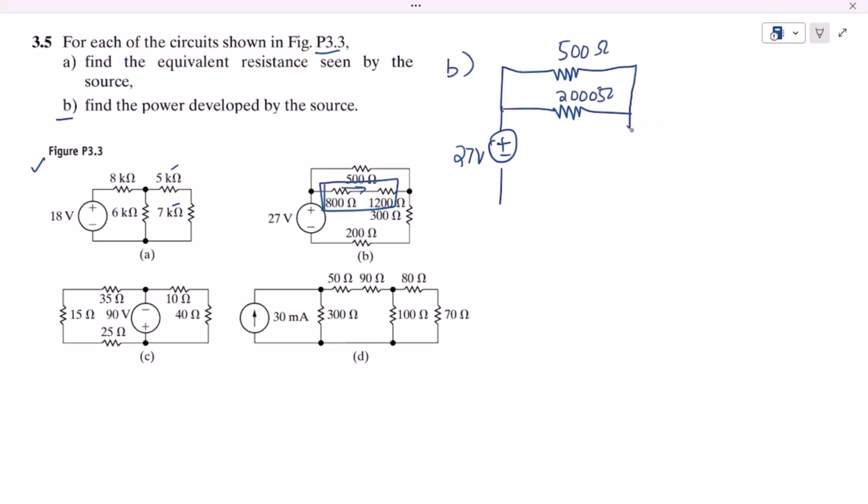Okay, and the other two resistors are here. We can see that these two are also in series, the same amount of current is flowing through them. We can simplify each of the series resistors here if these are in separate branches, because it doesn't matter whether these are in the same branch or in other branches, and it also doesn't matter whether we find the equivalent of them initially or at the end. So I take this 300 and 200 ohm and add them together, and it will be 500 ohm because these are in series. So the simplified circuit is now here.